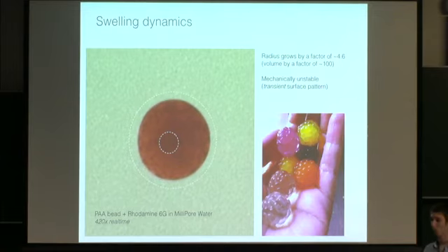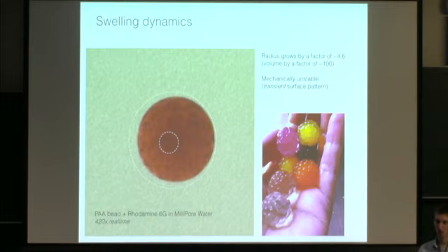So this is not a small deformation problem. So you cannot use linear poroelasticity for this problem. The geometry changes enormously, and so do all of the material properties. And so as a result, you really have to be careful with your large deformation stuff.